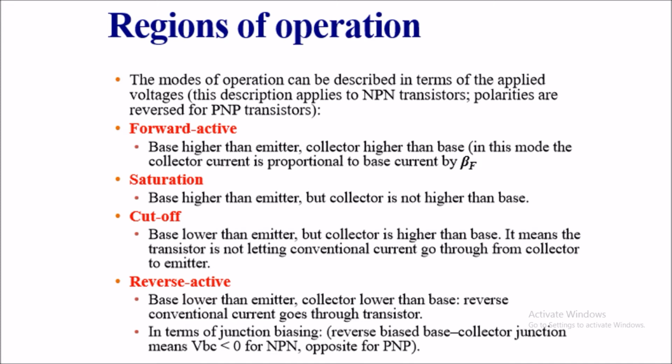In saturation mode, the base is higher than the emitter but the collector is not higher than the base. Then cutoff: the base is lower than the emitter. When the base is lower than the emitter, this is cutoff.